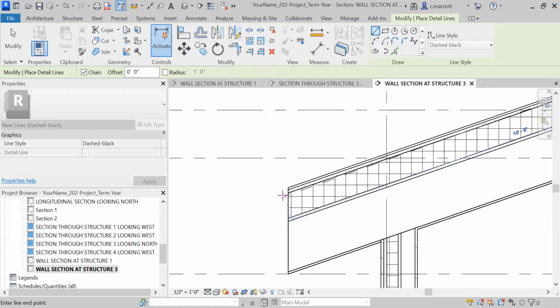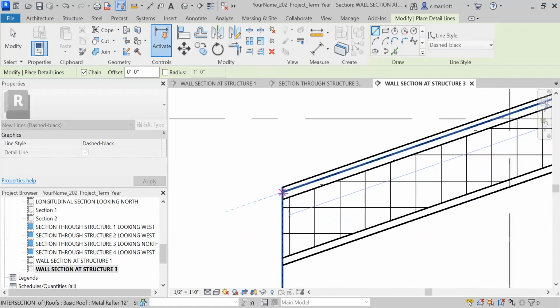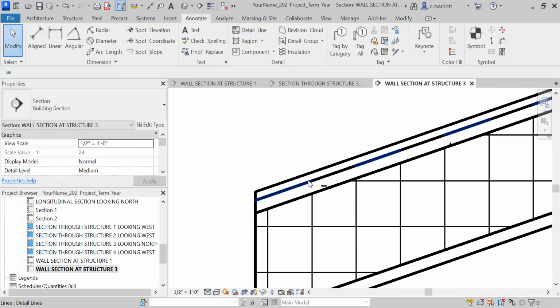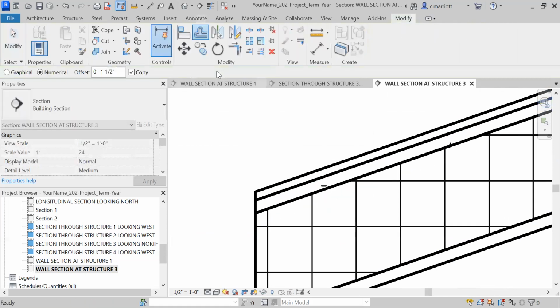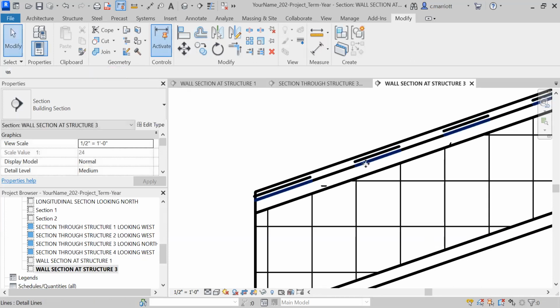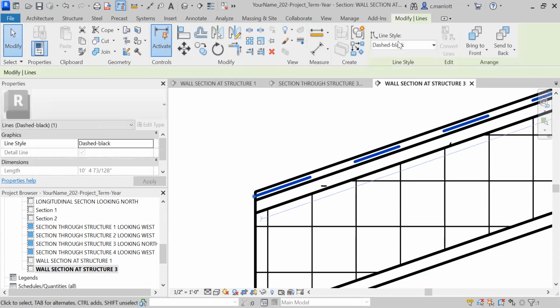It looks like I included a continuous line when I did the detail for the wood frame structure. So I've drawn this line and I'm going to offset it by 1/4 of an inch. Click on that line and move it over and then erase the original one. I think they're a little too far apart. So let's see what else we can find in here.